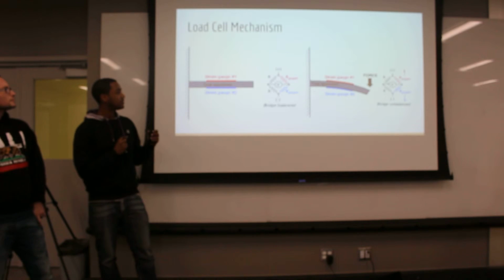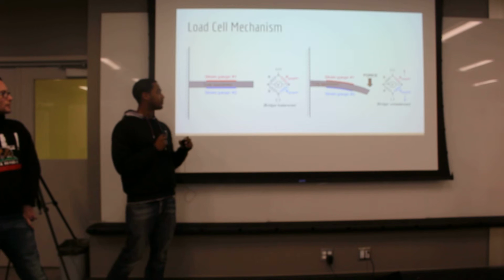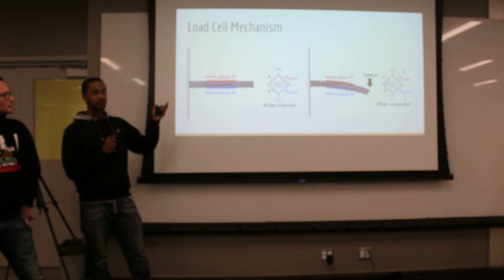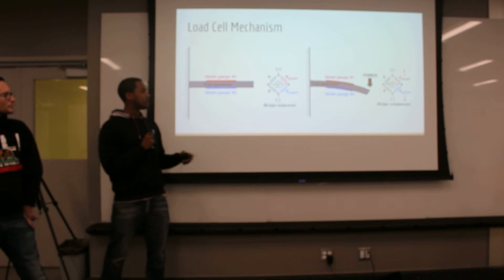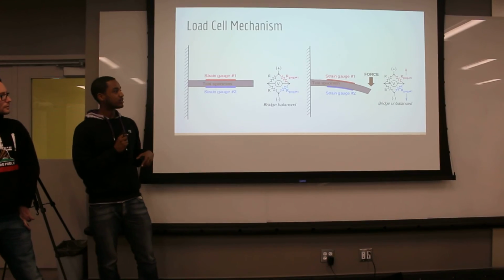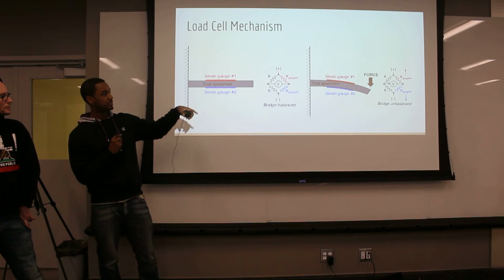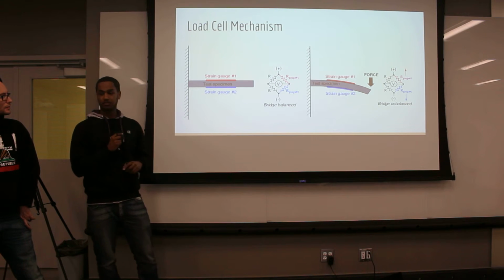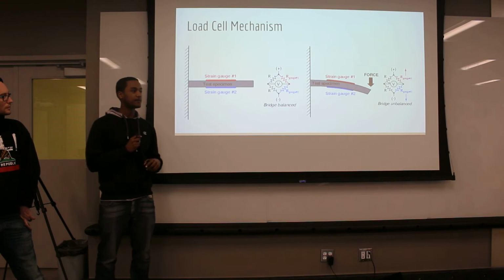So this is a nice drawing that we found that shows the mechanism that we just talked about. As you apply pressure, you see that the straining occurs, and as it bends as well, you see in the Wheatstone bridge how it affects the resistance.